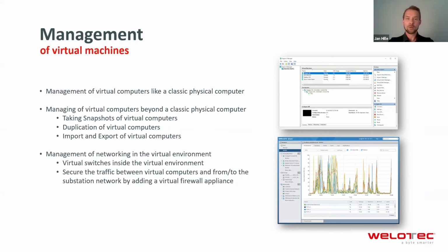Meaning that the traffic between the virtual machines will never leave the hypervisor system. It will stay inside the virtualized solution and will not cause any load on the substation network, and also will not be visible in the substation network, meaning it's a small attack surface there.